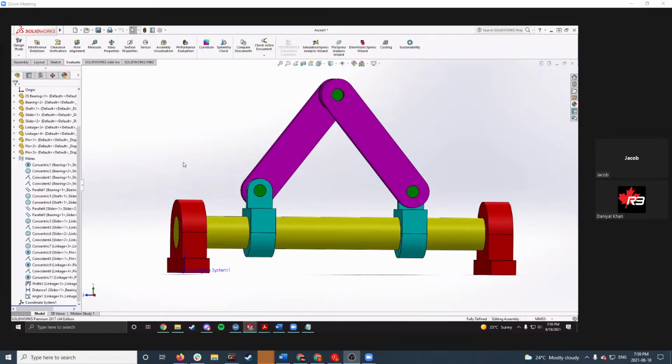I think the only case where they really are finicky with that and where I've seen real struggles is if they give you a ball joint and you need to make sure that the angle of the linkage attached to that ball joint relative to another face or line, the angle to that is specific or something like that. That's where you really need to worry and make sure you should fix rotation and double check your mates there really, really carefully. That can be a really tough spot to catch yourself making mistakes.